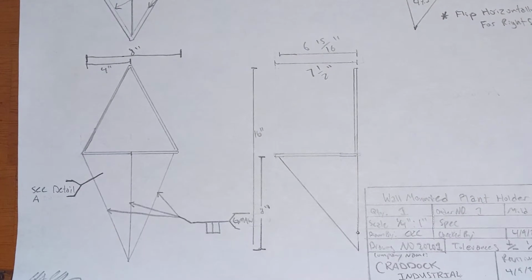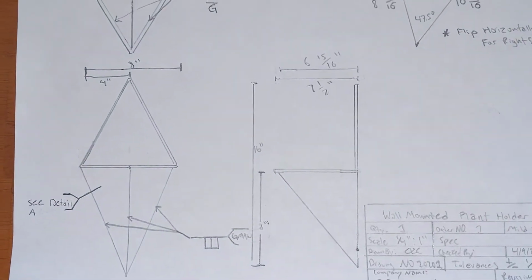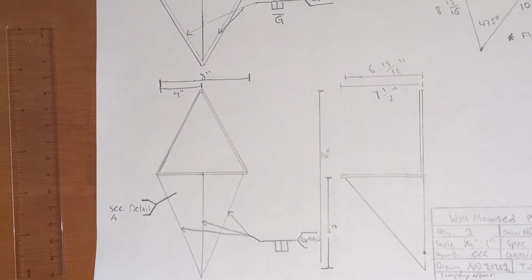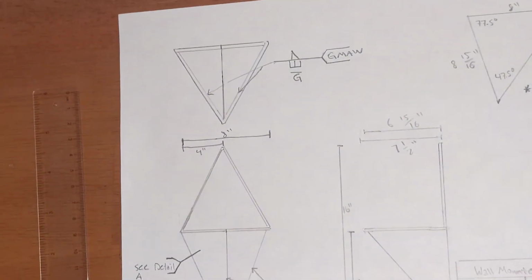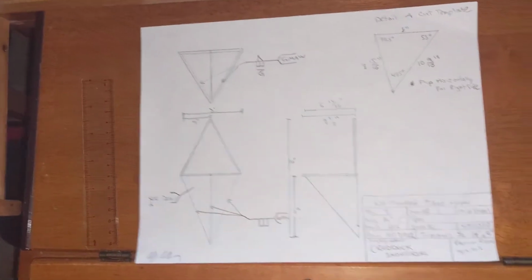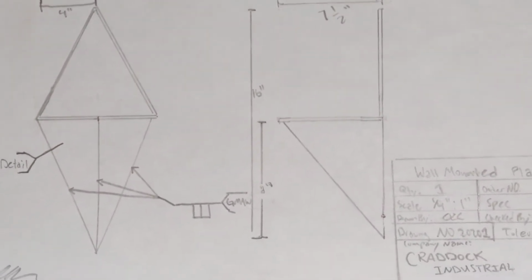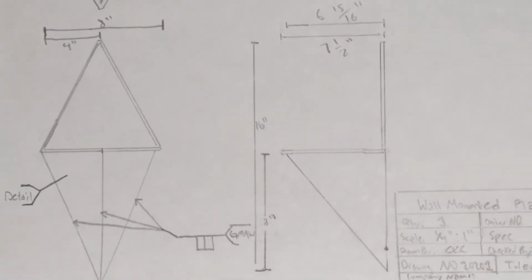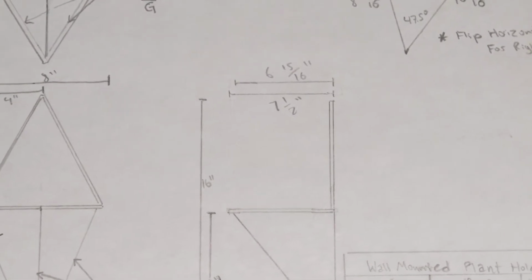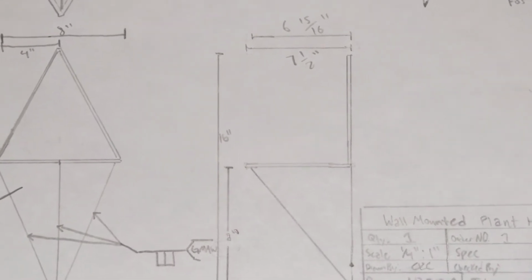This gives us a viewpoint of what we'd be looking at from above the product. We'll also see over on the right side, because it's to the right side, we can see what it looks like to look at this product from the right side when it is complete. Notice by doing this, I'm able to leave dimensions that measure in both views. So between our front view and our top view, I have our overall width of the product. This is 8 inches if you can't see that. I know this is hand drawn here. But we also can do it with our front view and our right side view. So we know that this bottom section down here where the plant is actually going to sit is going to be 8 inches as well. And the overall dimension I've put is going to be 16 inches. And then you see I have how far it's going to stick out. I've got 6 and 15/16 to the inside. That's just for the sheet metal that you're going to see here. And then I have 7.5 for the round rod that I use to line the edging on the top.